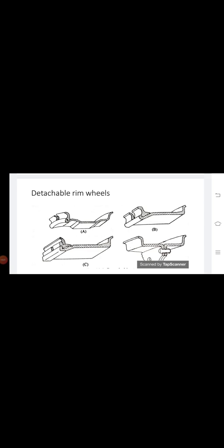In the wide base two pieces rim, it is made generally with one fixed flange integral with the rim base and one split detachable flange. The rim uses 5-degree taper seats for the tire beads. One of the detachable flange sides is integral with the flange.